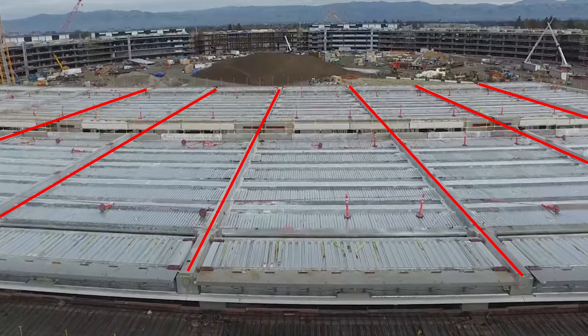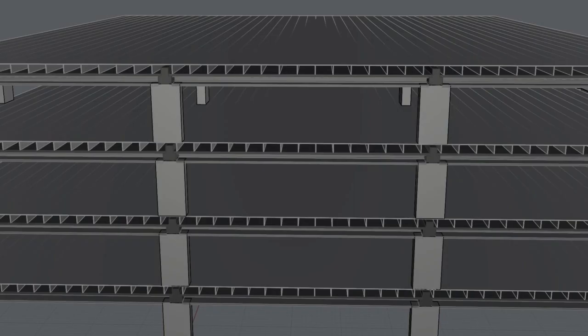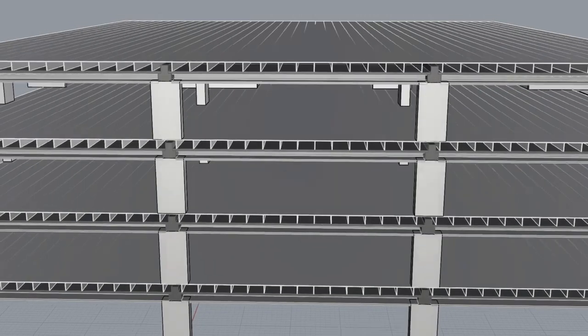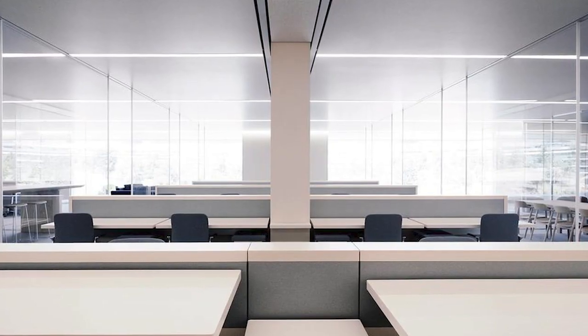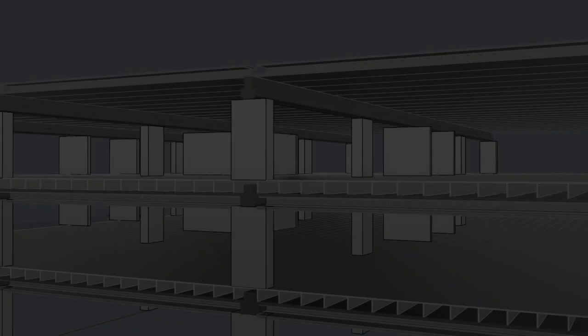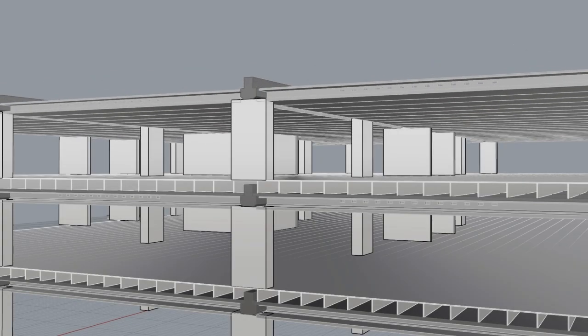These girders repeated themselves at every interior radial grid line. The girders also had to perform as collector elements, delivering more than 500 kips of force to the shear walls. The surface space below the girder was shrouded with either an architectural beam cover or partition framing where walls were placed. Next, we move on to the void slab.